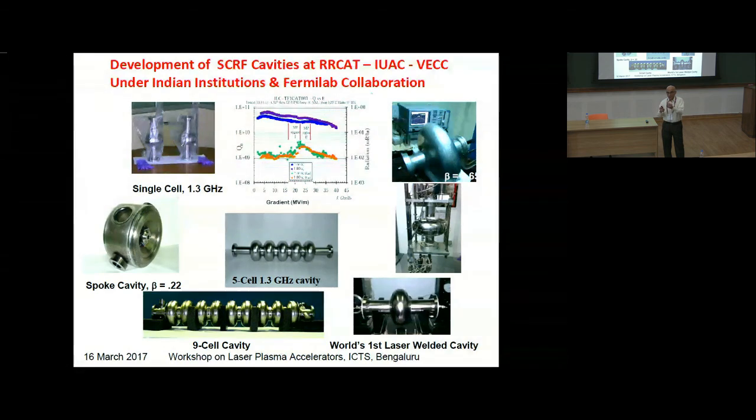But if it encounters a very small spot which is non-superconducting, the heating will just go on. It gets heated, it glows as a hot spot, and it kills the superconductivity immediately. So the whole cavity will quench, all the power will be reflected back, it can damage your system, and there will be loss of helium. So these surfaces have to be extremely pure, and no impurity is tolerated.